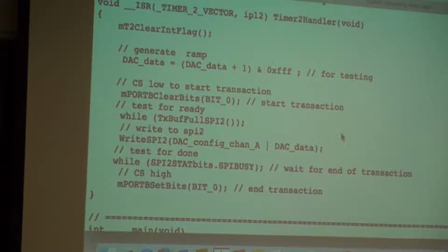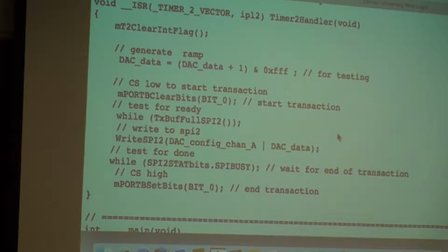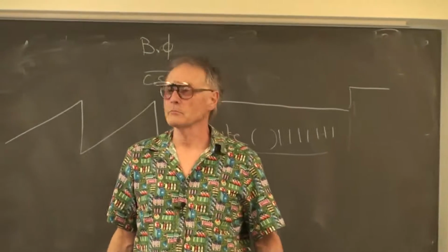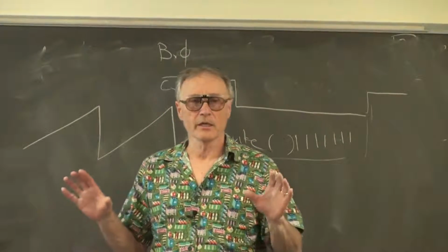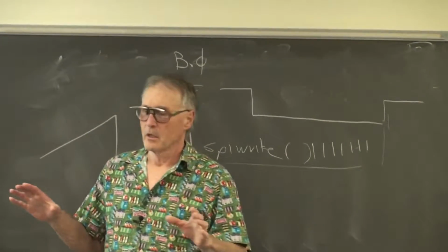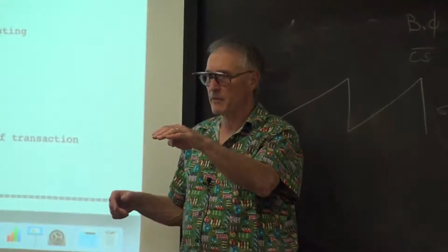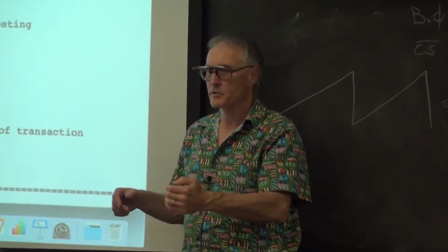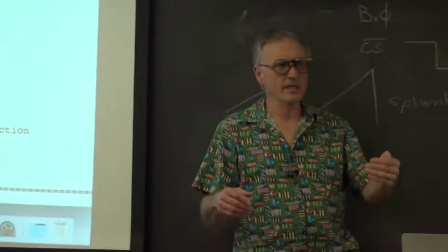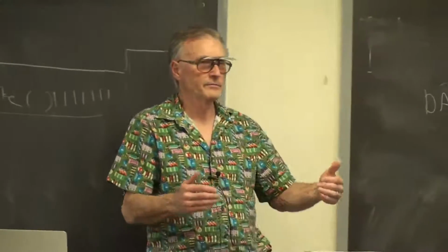I'm going to talk more generally about SPI next time, because there's a couple of quirky things you need to do, but the basis of it is you're sending a serial burst that's generated in hardware. You load data into an SPI register, and the SPI coprocessor turns on, generates 16 clocks, clocks out the serial data, turns itself off.